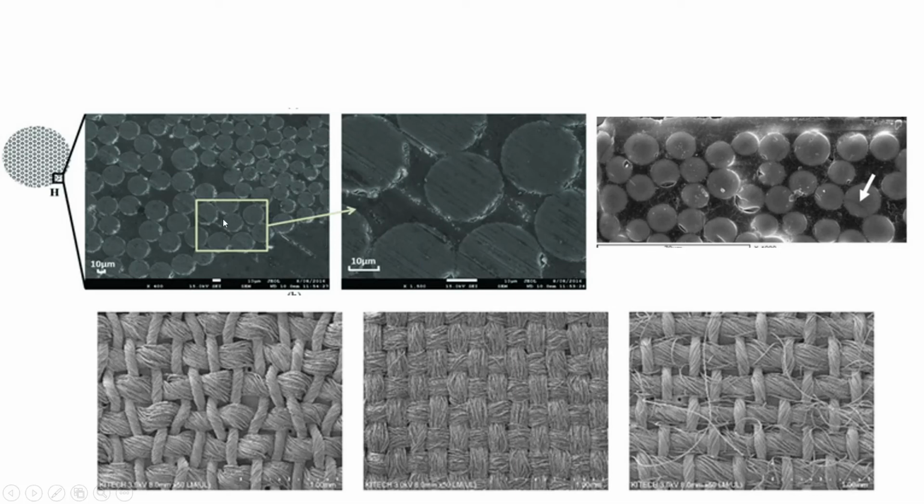So we have enlarged this image here. This was the image which was used for evaluating the air voids present in the bonding between carbon fibers and the matrix. This is a cross section of the carbon fiber or glass fiber, and this is again another cross section. We have these glass fibers, and this is the matrix material. And these are the air voids.